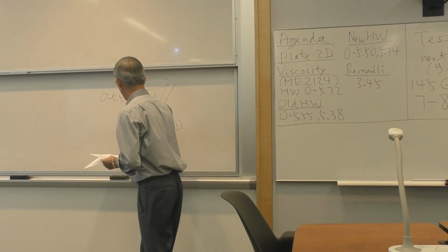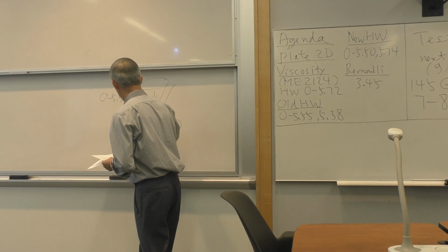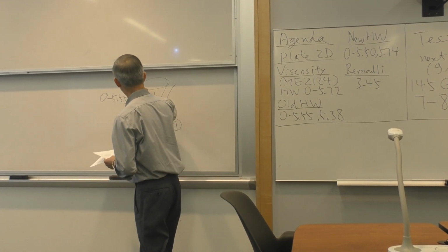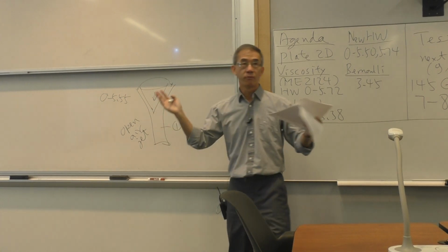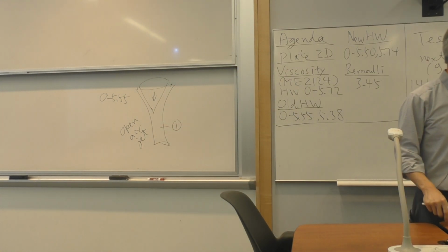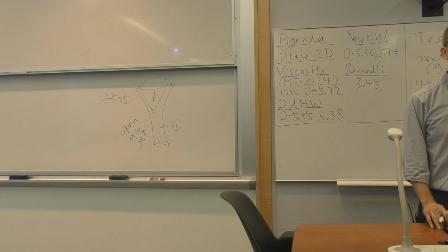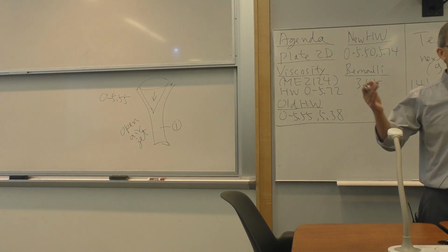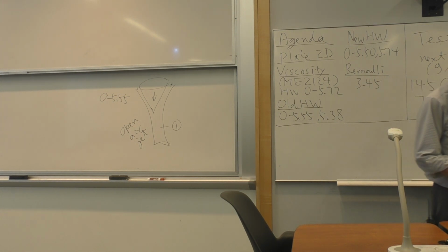This is an open air jet. And what is the pressure after it's split off on the cone? Atmospheric. Do you get it? It's a free jet, open to atmospheric. Contrary to that, I have a pipe, a tube, plumbing, that is containing the water inside. Can the pressure inside here be atmospheric? No. It has to be higher.